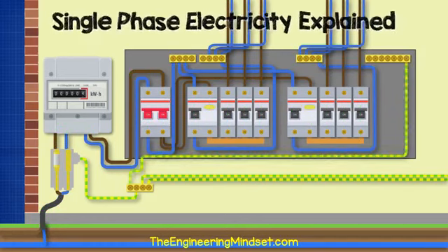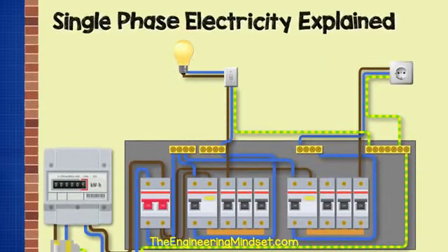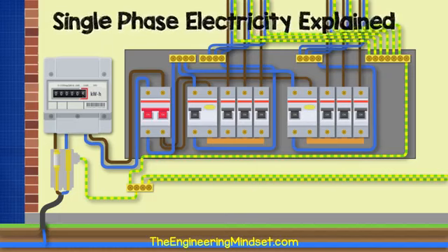These are called the earth cables. This earth cable usually runs along with the phase and neutral wires into the fixtures such as light switches and plug sockets. Some appliances will also use an earth wire for added protection, typically if the device uses a metal casing. The earth wires will connect from these fixtures into the neutral block with the consumer unit. All the earth cables for each circuit then connect into the earthing block in the unit.